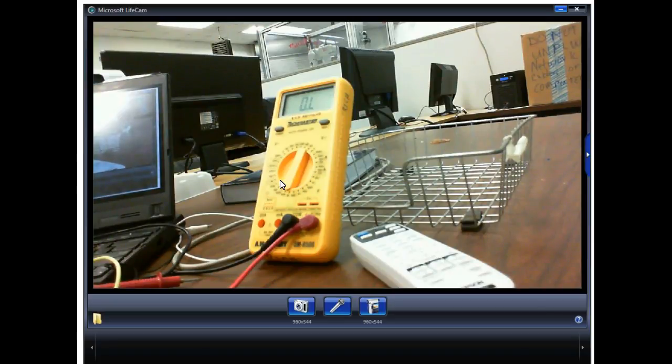So these are the two predominant configurations out there. Common emitters are probably the most widely used because they get power, voltage, and current gain, right? So they have a high power gain, but when we say a high power gain, we're still talking about milliwatts, right? And when we need real high current gains, common collectors get the job. Common bases are used a lot in extremely high frequency, but you have to give those a lot of power because they have no current gain at all. They have a real good voltage gain, but in fact their output current is a little less than the input current.